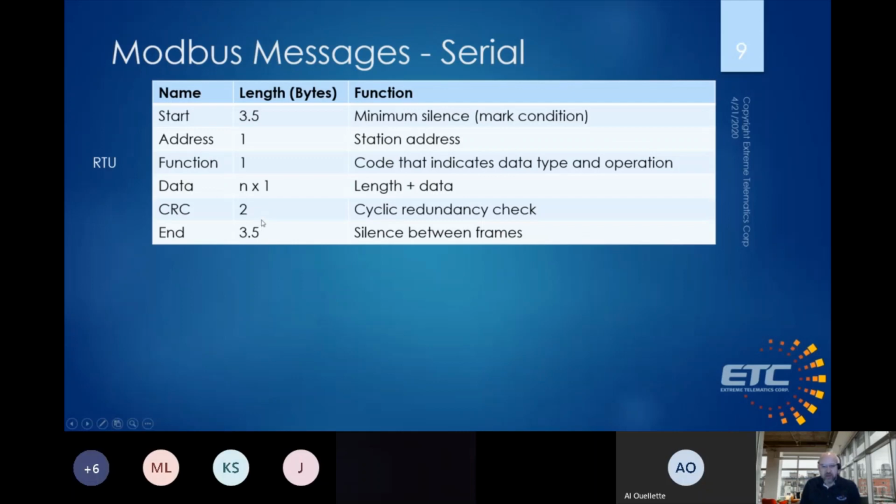So in a lot of protocols, like when you're doing Modbus frames, there has to be a retry mechanism from the master, so that if the slave throws away the data, you have an opportunity to retry that operation. And then, of course, the silence frame at the end. Now, this is all for RTU. So once again, this is the more efficient way of doing it.